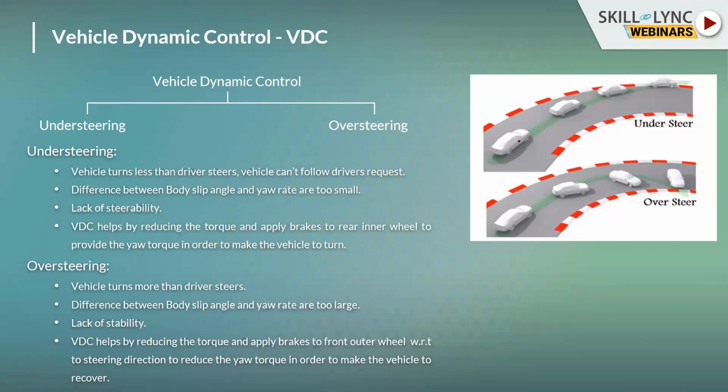Due to the weight shift, the CG position of the rear end tends to shift. Because of that, the rear wheel will come around. The vehicle will tend to rotate with the front axle as the center point. So because of that, the oversteering will happen.